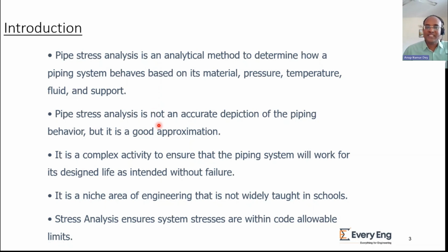Sorry, sir, is support provided before stress analysis or after stress analysis? Initially, piping layout designers or piping layout engineers will be routing the pipe, and wherever existing support possibilities are there, based on that they will be providing us the locations, or they will be marking all supports as rest support, because there are mainly three types of supports that we use in stress analysis: rest, guide, and line stop. So during that time they will be telling us the rest support locations specifically. Based on that, we will be modeling our system, and later after stress analysis, we will be finalizing whether those locations are acceptable or we have to make any changes, and also the type of support we will be telling.